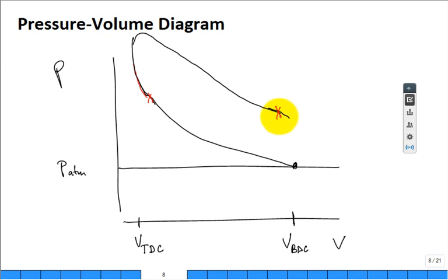That's the exhaust valve. Now, this is why you have mufflers. Some of you don't. You drive by my house maybe a mile away, and I can tell you don't have a muffler. But this is why: when that exhaust valve cracks open, this pressure is much higher. And it can create choked flow, Mach 1, right through the passage of that exhaust valve, and it makes it really loud. Really loud. Now, that also leads to a very rapid reduction in pressure when that valve cracks open, because a lot of gases get out.